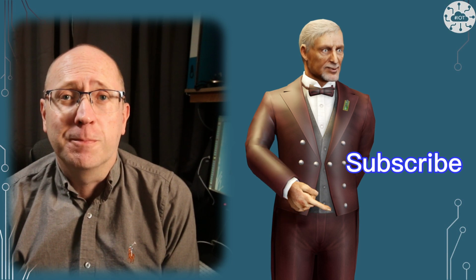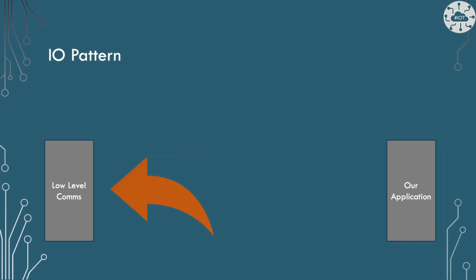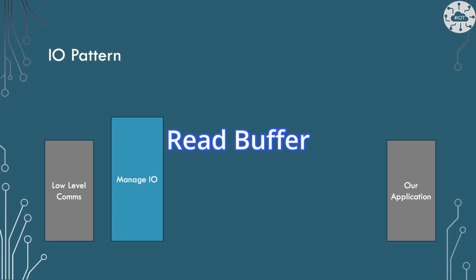I'm going to break down this communication pattern into a bridge of tasks or agents. We have our low-level comms services provided by the SDK or libraries, and we need to bridge that to our application. The first thing we need is something to manage our I/O, so to be able to read messages from the comms services before the buffer overflows, also to handle when messages are sent out. You may also see that agent doing services like keep alive messages to make sure the communication channel remains open.